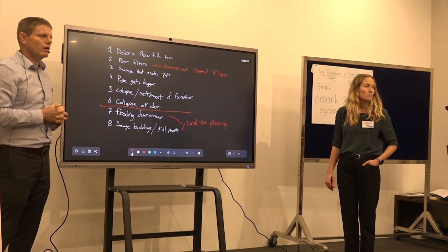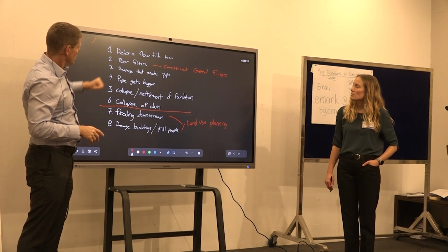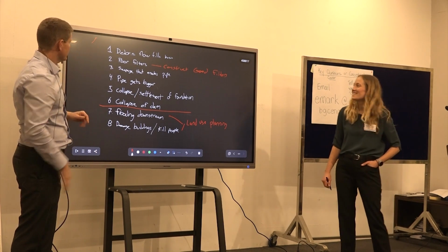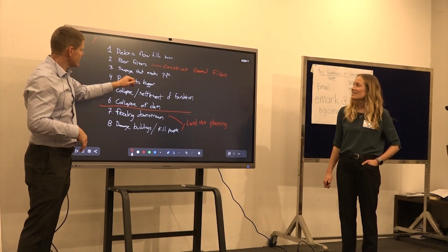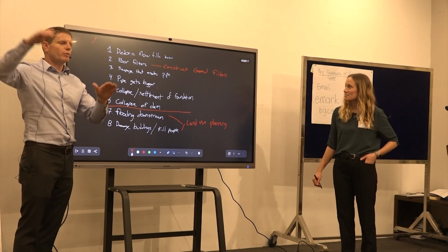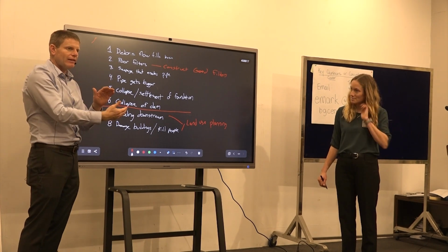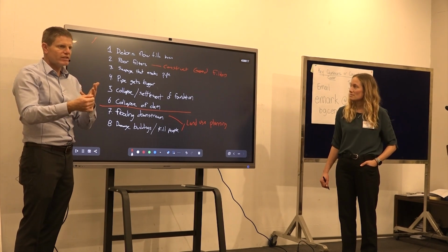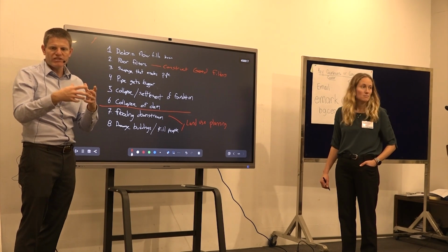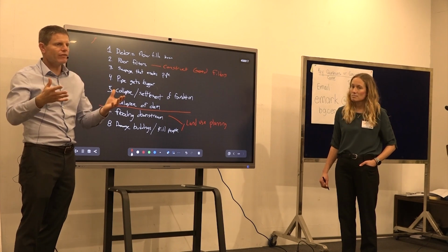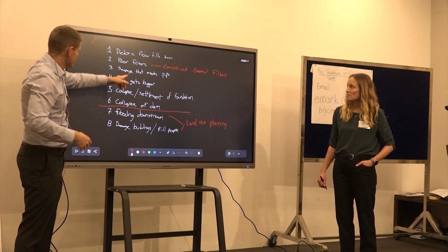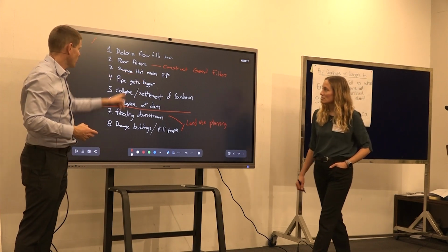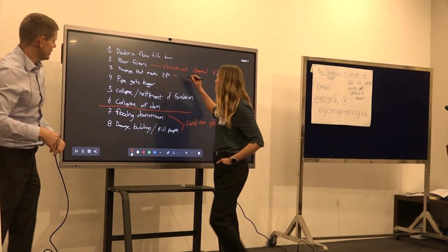Okay, then for problem number 3, I think insertion of sheet pile to increase the length of the seepage path. A great idea. So we can reduce the seepage gradient. If we increase the seepage path, then it reduces the seepage velocity and the gradient, which reduces the ability of that seepage to remove materials. So that's a great idea. We can increase the seepage path length with a sheet pile so that we don't initiate a pipe.